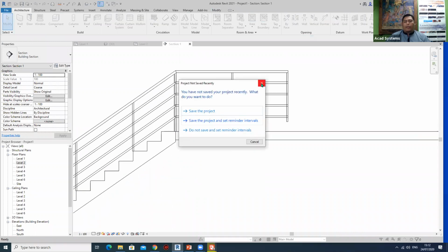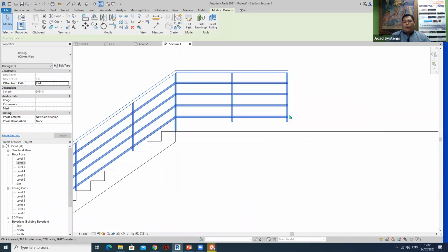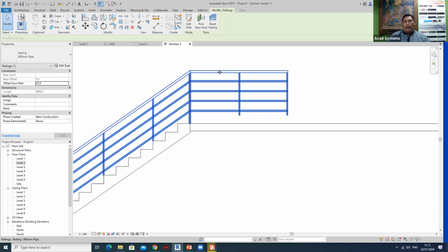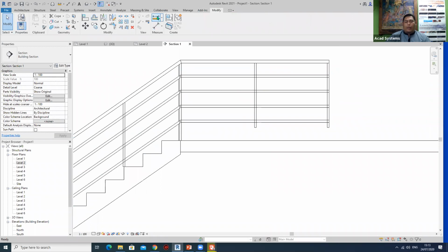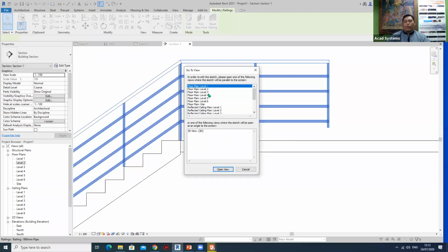And the other part of the flat railing will turn out hanging like this. What you need to do is to create new railing settings to define the actual height for this angle. For instance, if I'm measuring this part, this would be 248, and the total height would be 1073. So this is the new railing type that you need to create to solve this issue.